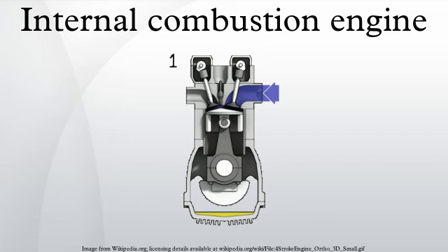Some systems disable alternator field power during wide-open throttle conditions. Disabling the field reduces alternator pulley mechanical loading to nearly zero, maximizing crankshaft horsepower. In this case the battery supplies all primary electrical power.